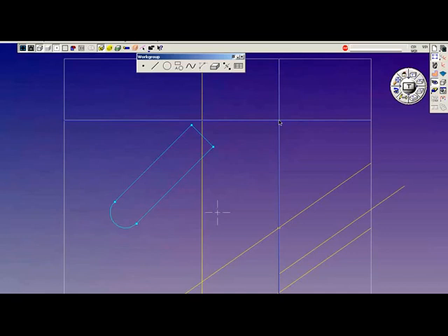Having selected the two lines, I keep the cursor on the geometry, I right mouse click it, and I tell it to connect. The pull-down menu on the right mouse click has four options. The last one is connect, disconnect. We click on that, and we generate a connector point at that intersection. Do the same thing down here. Shift, drag a small window over the intersection, right mouse click, connect.